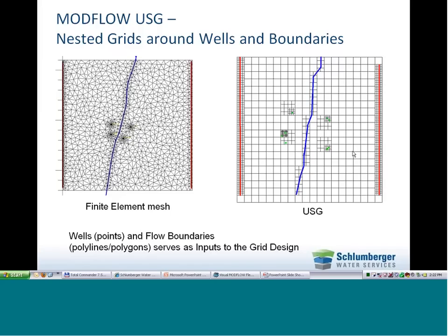One of the other benefits of VMODFlex is that it's a 64-bit application now in addition to 32-bit, so you can build some pretty significant size models if you need to. Obviously there are slowdowns when you need to populate that grid with the conceptual objects, when you do the translation, and also at runtime. I haven't really reached any limits yet that I'm aware of. Certainly you can build parent grids that go up into several 100,000 nodes, and also child grids as well.